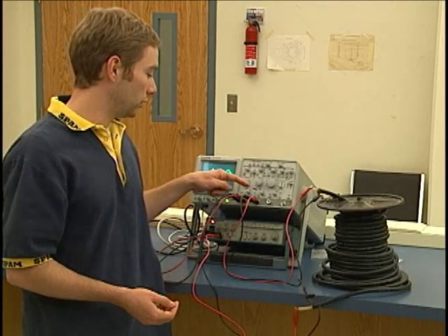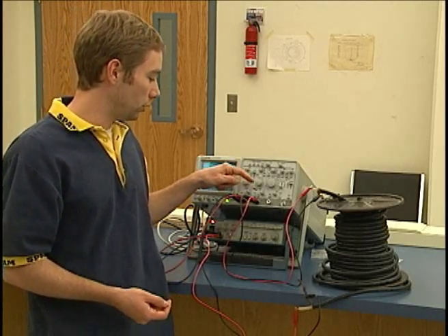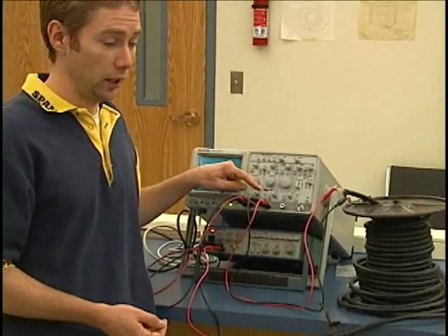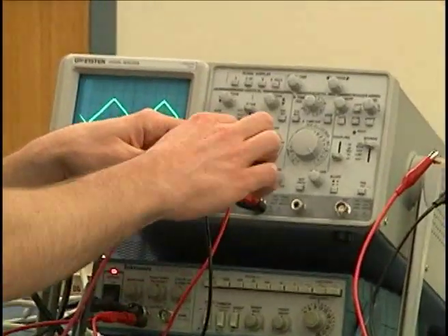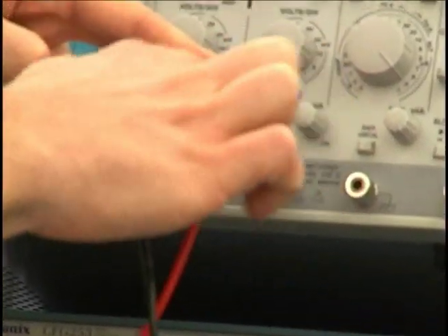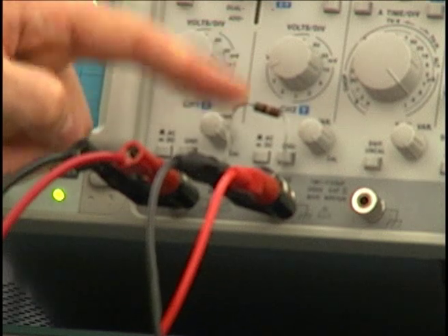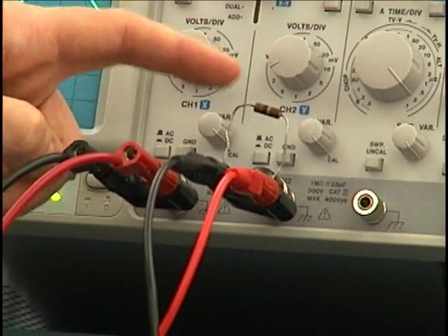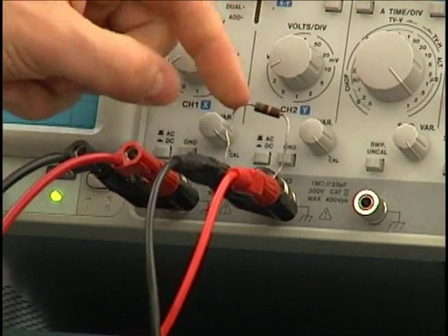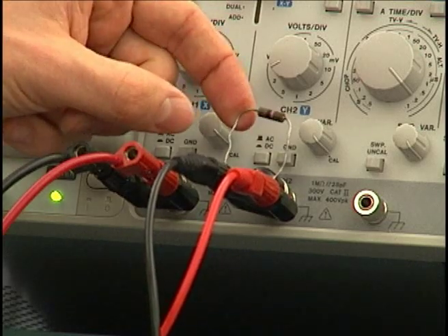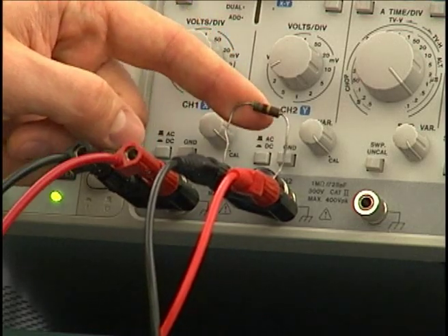One final thing you'll need to really remember to do is to include this resistor. You can put it in a few different places, but right here across the red and black, right on the oscilloscope's channel 2 input is a really good place to put it. The reason we need this is because this thing will help with the impedance mismatch.